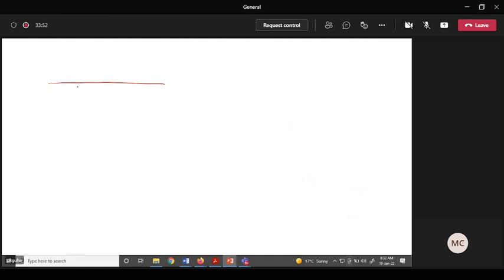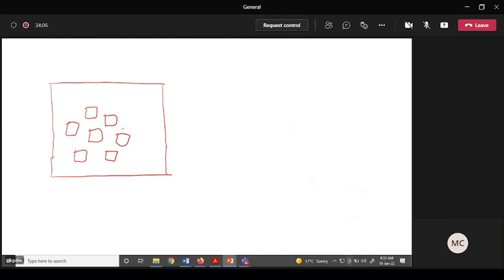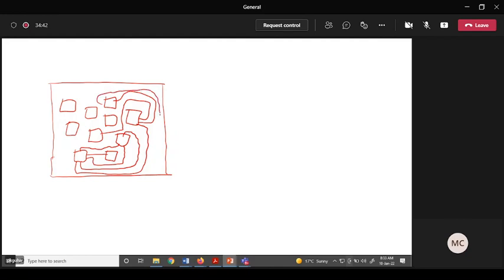If this is the top view of my silicon chip, which contains several thousands of devices depending on your application and requirement, such as MOSFETs, resistors, capacitors, and so on, I'm just representing them through blocks. If I need several connections and I have only one metal layer, I need a lot of space to connect all these terminals through metal lines, which is usually the case. With only one metal layer, say metal 1, I need a lot of space.